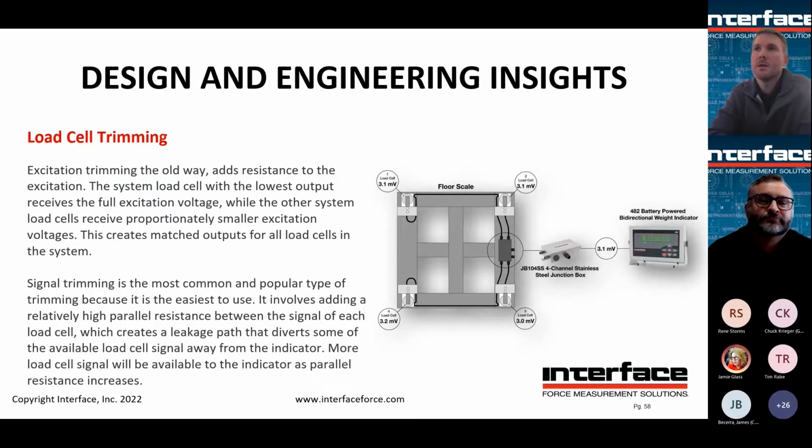Next. So load cell trimming, I kind of touched on this earlier. One of the nice features of the weight check is that we have matched outputs, but typically your cells are going to be plus or minus a few decimal points, and it's going to be important that they are all matched. So, there's 2 ways to do it. You can do excitation or signal trim, pretty much, determine how much voltage is going to the scale or determine how much signal is coming back. And within the junction box, there's potentiometers in there to kind of play with how much power is going back or forth. And essentially you want them all to be matched.